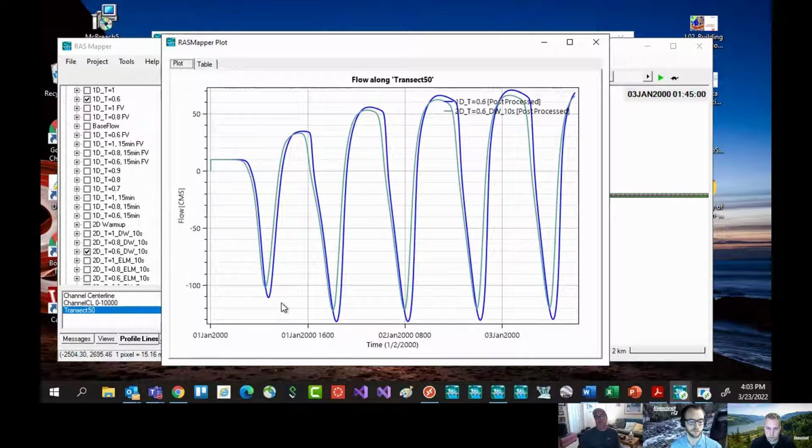And if you're working in a river system where the slope is fairly steep, well, then gravity and friction are really controlling almost everything. And that's where a diffusion wave method will shine, is in steeper slopes, okay, or at least medium slopes. But once you get into flatter slopes and you have more wave propagation, where what's happening downstream affects upstream, and especially if you get into tidal, tidal coming in is all about velocity, right? As far as how much it's going to propagate up and propagate back. Okay, so if you don't have those velocity terms and derivatives, then that alone is why you're seeing this difference, more so than anything related to time step or theta. It's the fact that you don't have those velocity terms.